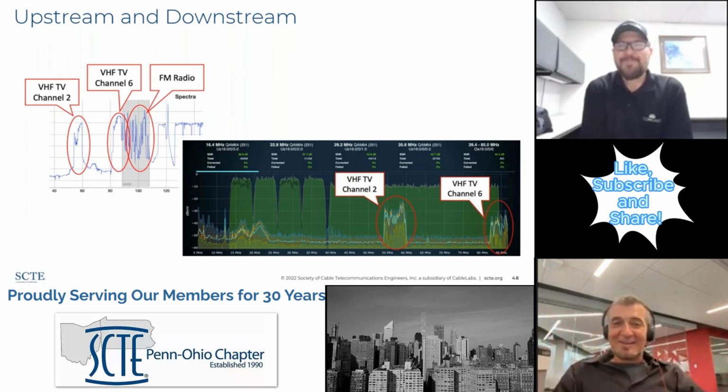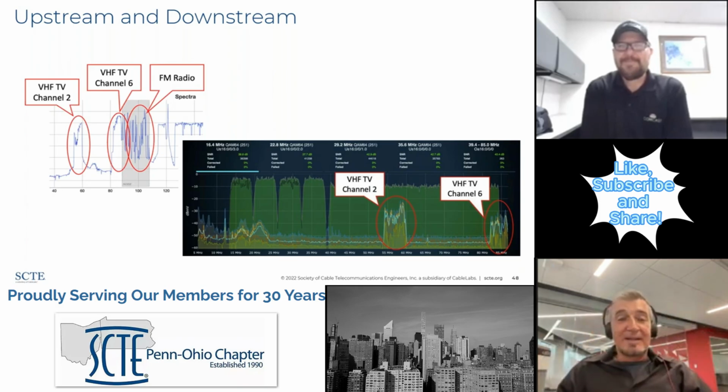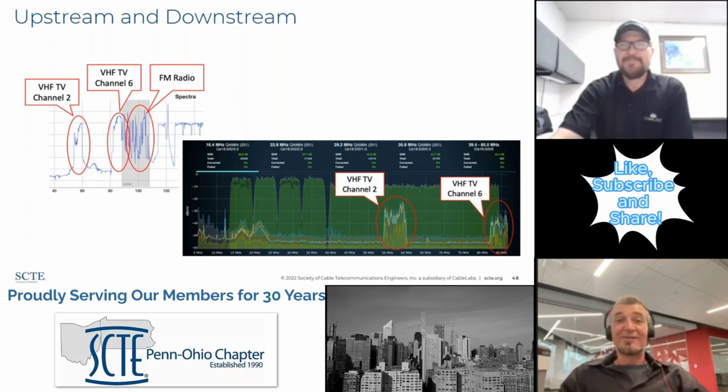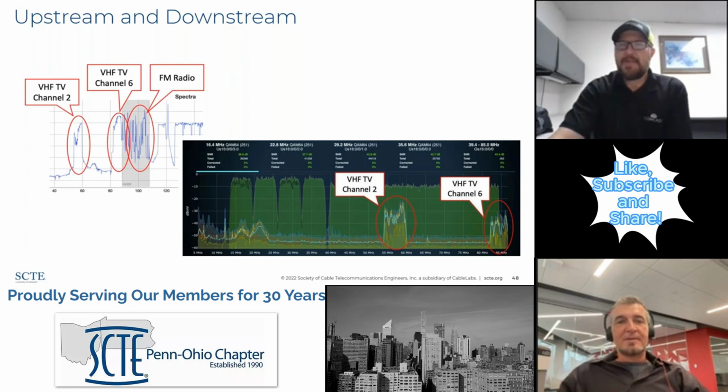And this is going to get really tricky as we start to go full duplex, for example, where upstream and downstream become one and the same. And so we're going to have to pay a lot of attention to things like ingress and egress at different places in the frequency spectrum, because now they're going to affect everybody, not just that one customer, when we change directions.